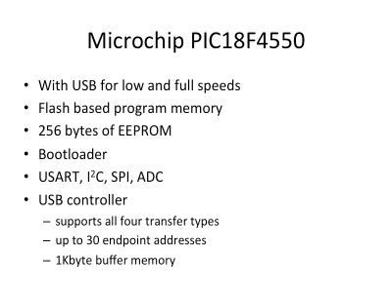This chip also has other interfaces, UART, I2C. For USB, it supports all 4 transfer types. It supports up to 30 endpoint addresses, and it includes 1 kilobyte of buffer memory.